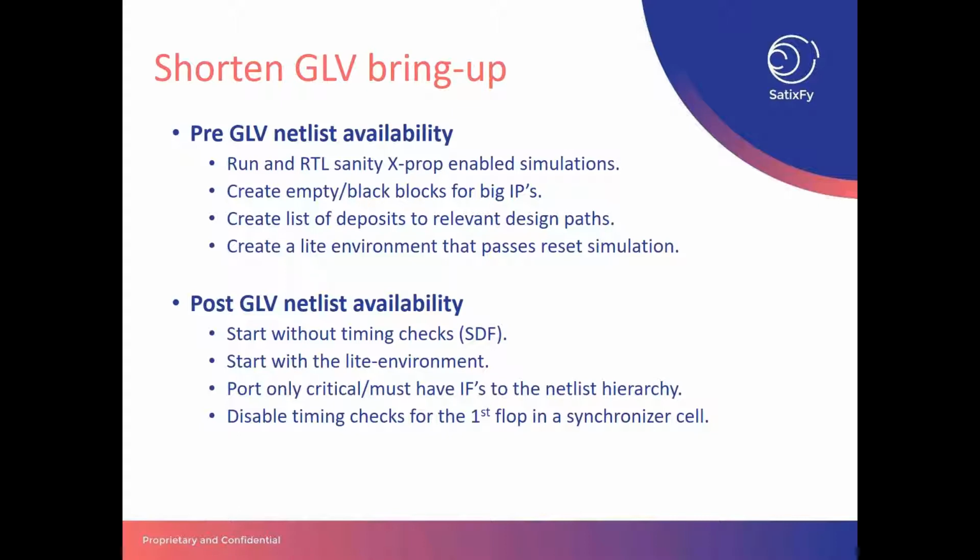And even in the light environment, if you are using some VIPs connected to some of the interfaces in the design, you would need to port those that must be running and enabled to pass the first simulation. The porting is basically to remap the interface to the new hierarchy in the gate level, which might be different.